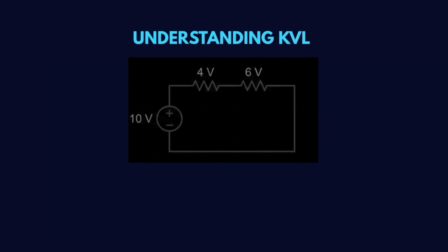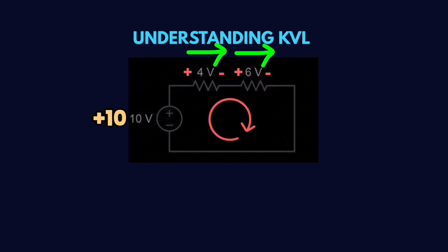Next, you need to know about sign convention. This is where many students lose marks, but the method is actually easy. While moving around the loop, crossing from negative to positive causes a voltage rise. Hence, you should indicate positive voltage across that component. Crossing from positive to negative causes a voltage drop. Hence, you need to consider that voltage as negative.